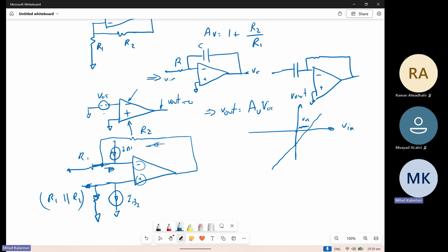But on the other hand, we have the other port, which is pretty much similar, and it is also drawing some current. So if we connect almost the same impedance, we are trying to minimize the voltage difference between the ports, right? So overall, we minimize this voltage difference because of the bias currents at the input of the op amp. So it will not generate extra voltage at the output, right?